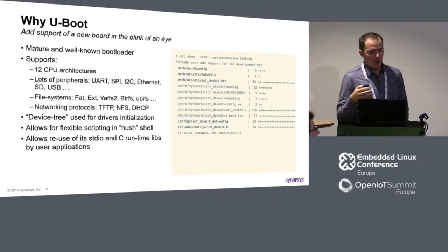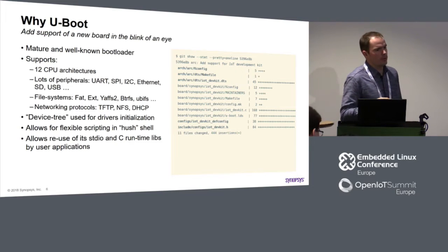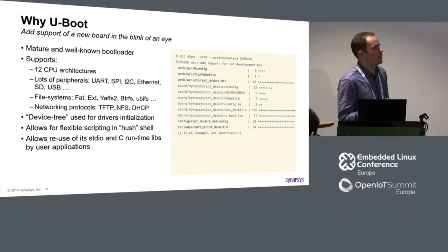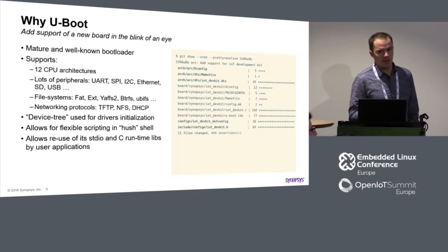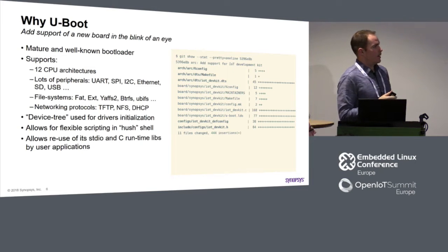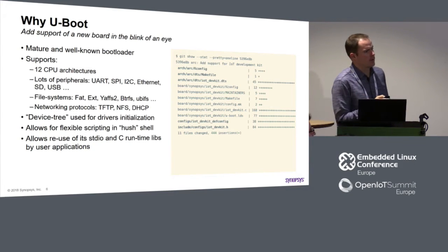And so why use U-Boot here? Again, we have support of pretty much everything here. You may see a lot of architectures, including ARC. We have support of different peripherals. We have support of that DesignWare UART. We have support of the DesignWare USB OTG controller, and we have support of SD card as well. So nothing to do here. We have support of different file systems, and the FAT file system is here as well. So again, nothing to be done. What else? It supports networking protocols, but we don't have networking on these boards. But anyway, that's an interesting benefit.